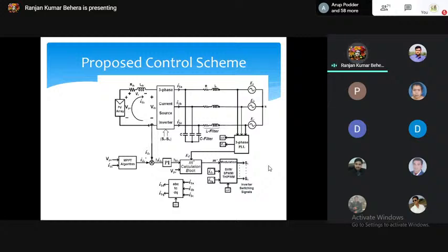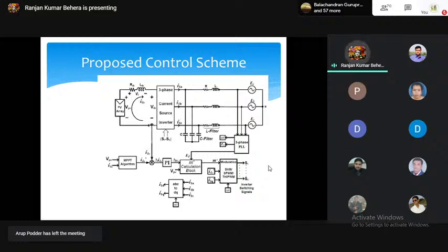Sometimes we also use a small transformer just to get the phase of that system. So this phase lock loop will fix your input and output frequency. They both have the same frequency, F1 equals F2. Second, if there is a constant phase shift, it will maintain it at the output also.